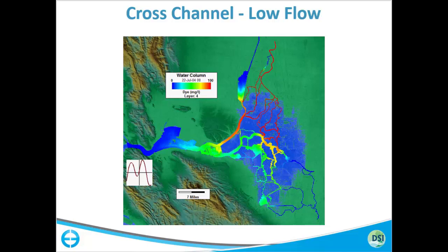So the main purpose is, from this study, what they found is that in the areas connected to the open boundary, the TSS distribution was more controlled by resuspension from the tides. But on the shallow areas, the sediment distribution or sediment impacts were more from the wind effects. So the wind was really critical in these areas.